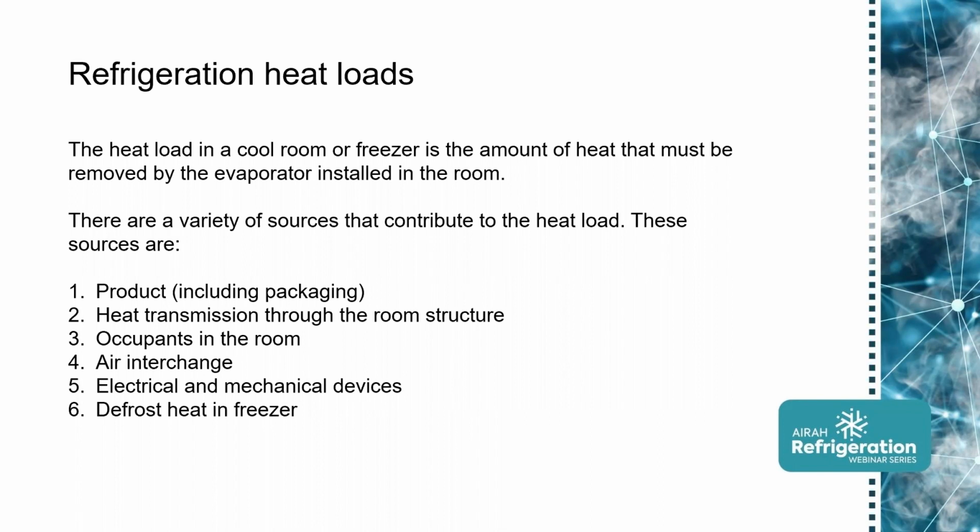Also, in the refrigerated facilities or the cold space, you will have mechanical devices like forklift trucks, and your conveyors and other material handling systems that have motors operating them. So the heat from the motors contributes heat into the room as well.